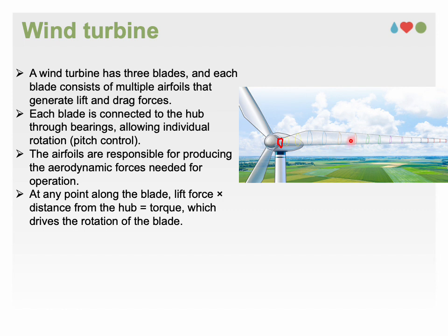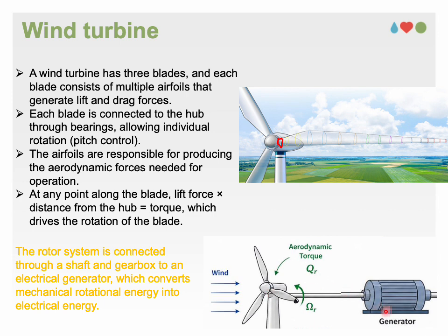The airfoils generate aerodynamic lift and drag forces, and the lift force acting at a distance from the hub produces aerodynamic torque which rotates the blades. The rotor system is connected to an electrical generator through a shaft and gearbox, converting mechanical rotational energy into electrical energy.